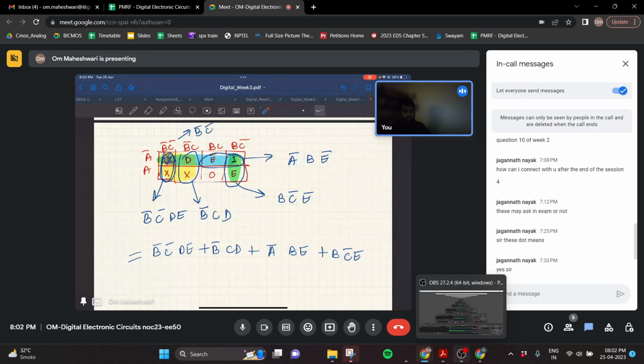Okay, so how do you arrive at this? What you write here is just the outputs, right? From a truth table, you just write, if it is A, B, C dependent, if Y is there, you write 1 0 1 0 or whatever it is. You write those ones and zeros here, right? Let's say it was not 1 or 0 in the output Y, it was some other variable E or F. Then you would write E and F here, whatever it is. And then instead of just forming pairs and naming it as B bar C bar, you will multiply whatever you are encircling also. If it has D and E inside, you will multiply D and E in this.